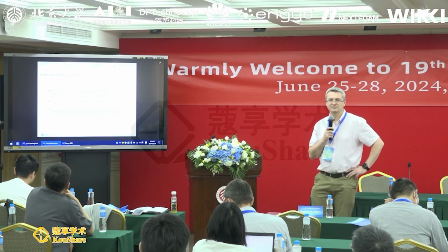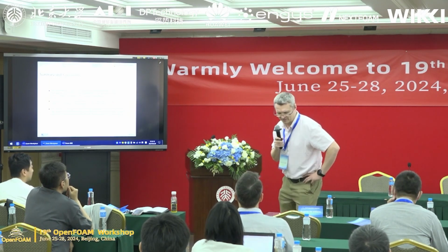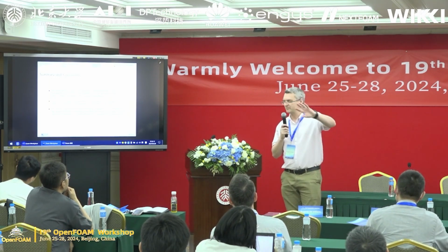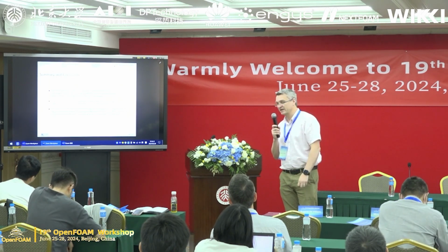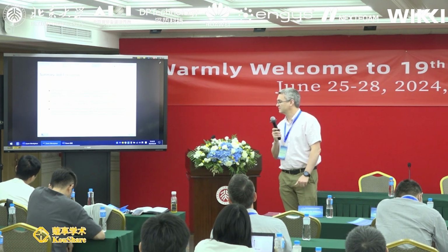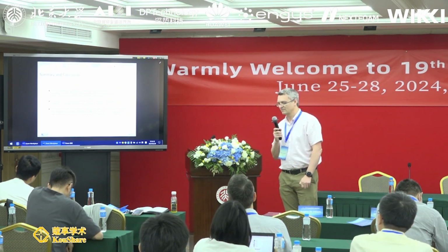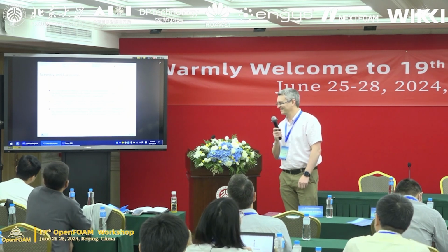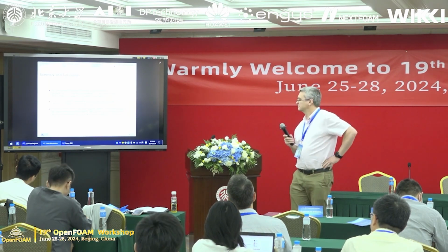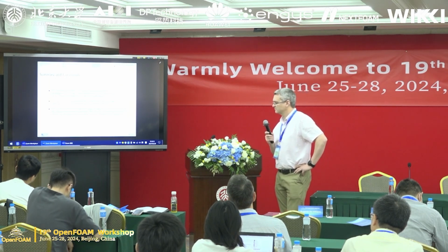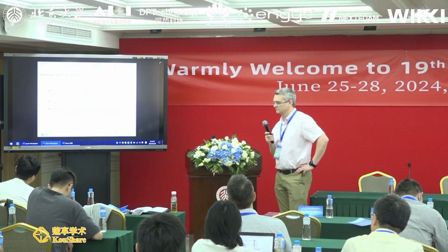Any more questions? I've got a question. Tessa, with the MRF, the blades are fixed at a particular rotational position. Do you think that influences the type and magnitude of the scour you see behind those turbines? Definitely, because this is a steady state simulation. It converges to a steady simulation. This is why we used MRF zones, and also because of the time limit that the students have. They only have 2 months for doing their masters, and this is why I decided to use the MRF zone. If we would take into account the rotation, the position of the blades, I suppose, yes, there would be a difference in the morphology of the bed, of the scour.